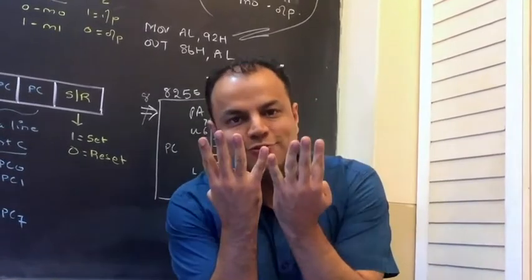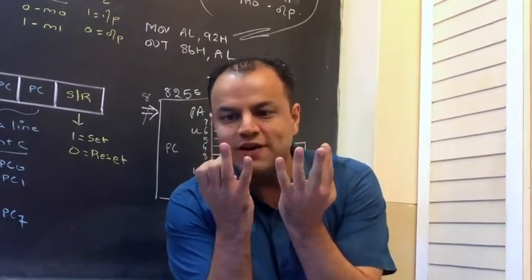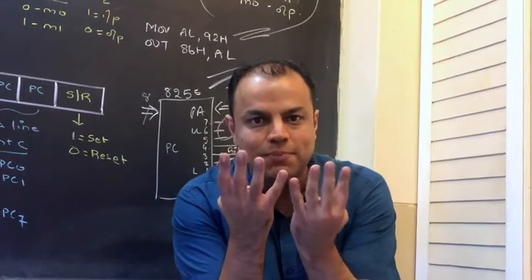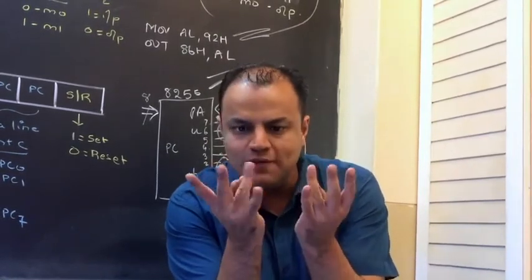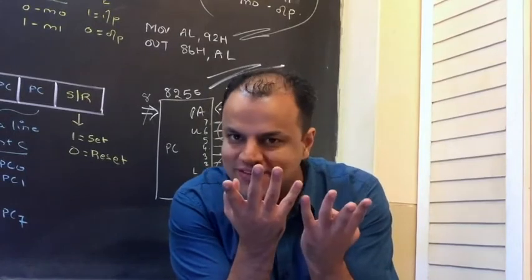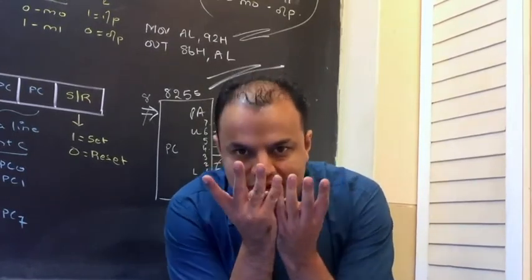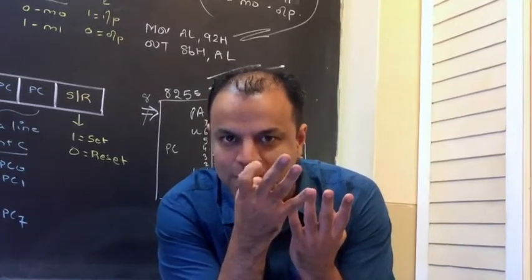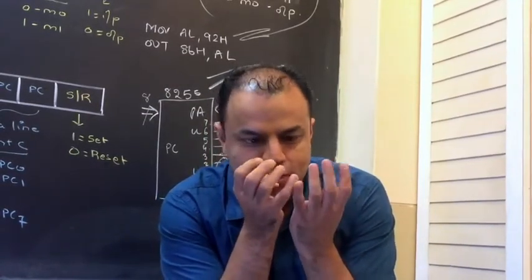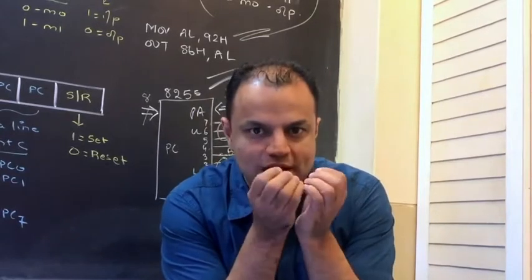These are 8 lines of port C. Imagine you've connected them to 8 different bulbs. You want to turn on this bulb, this one. You have no clue what these bulbs are doing. You can't even see them. You don't want to interfere with them. You want to individually make this line 1 or 0. If this feature was not there, to make any line 0 or 1, you would have to affect the whole